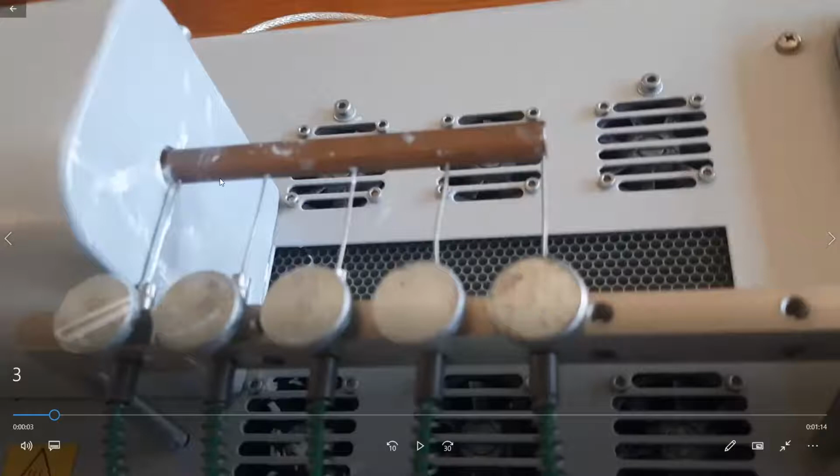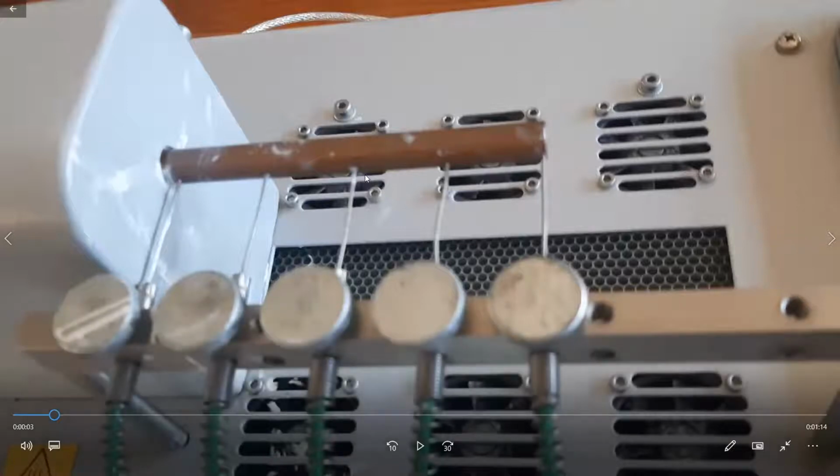We know the distances and the 5 different temperatures in 5 different places of this rod, and we know the diameter of the rod. Diameter is 10 millimeter, and we know the different lengths between these temperatures. Using those, we can calculate the heat flow rate, then the thermal resistance or thermal conductivity, everything.